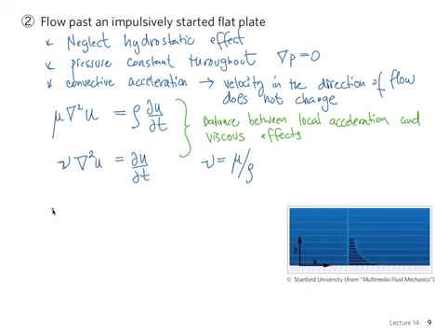The solution here is, say, we called it the impulsive start of v0. That's the velocity of the plate here, v0. In this case, it's moving that way, v0 times 1 minus an error function. This is one of the special functions. You can find it in your handbook of mathematical functions, or MathWorld. You know MathWorld? Do you know this website? That one. Error function, you can look it up if you want.